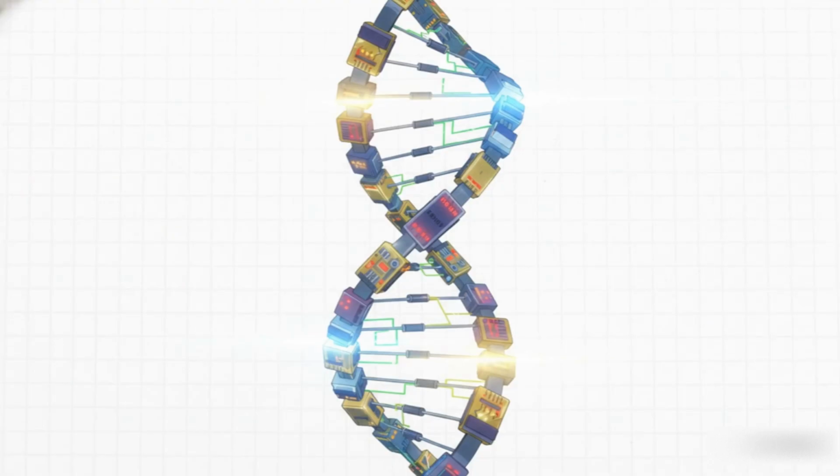So let's just pull this all together. These three core techniques we talked about, they are truly the DNA of modern microelectronics. You've got current steering for elegant and efficient biasing. You have active loads, which let us get huge gain without those big clunky resistors. And you have cascoding, the magic trick for multiplying gain way past what a single transistor could ever do on its own.